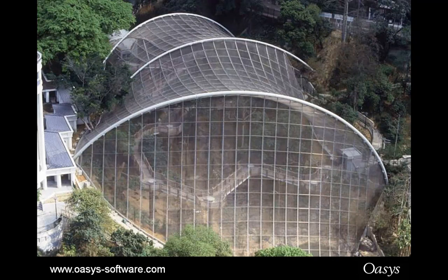Again, the forms, obviously you can see the double curvature of the barrel vaults there, but also the geometry of the arch is crucial. And this is a slender arch which is both supporting the cable net fabrics there and also is supported by the fabrics. Get the geometry right and the arch is very strong. Get the geometry of the arch wrong and it will buckle under load, or you need to make it very heavy duty. And this, of course, is the Avery in Hong Kong.